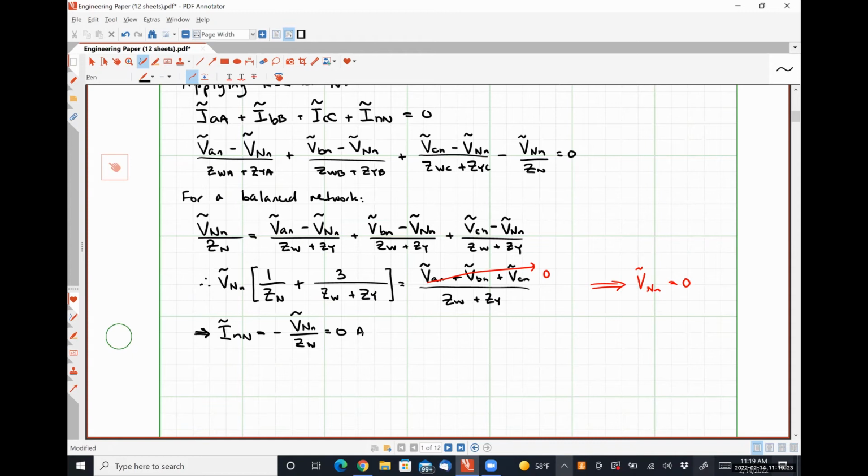If you were to look in the National Electrical Code standard, the size constraint for the neutral conductor is different than the size constraint of your phase conductors because it's not expected to actually be in use very often. So it's got its entirely own section in the code book for how to properly size that guy.